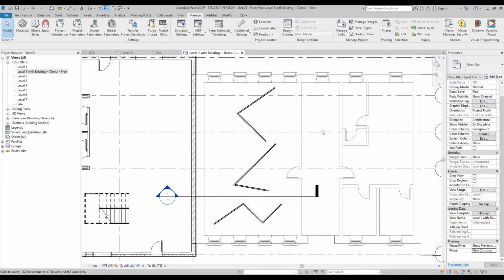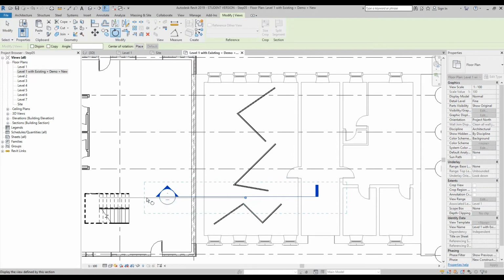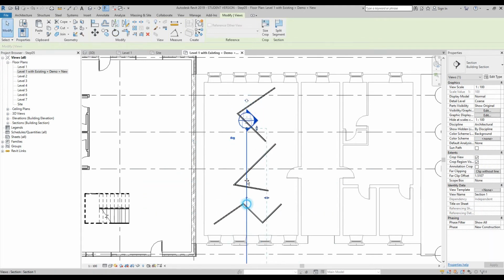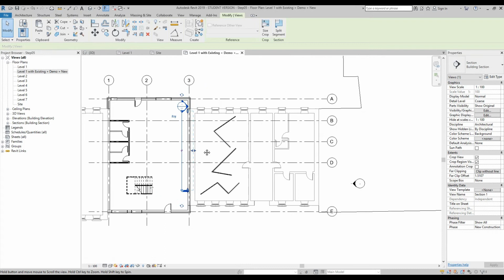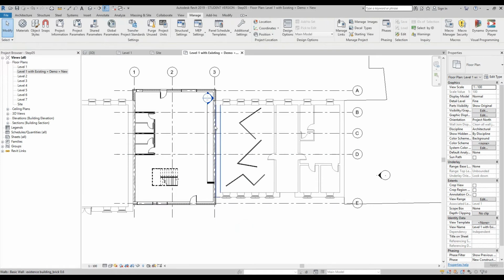So the next thing I want you to do is draw a new section, but as we've already got a section that's currently within our model, we can actually rotate this. So if you select it, the user interface will go green, and if we go to the rotate tool, it will automatically go to the center, which is absolutely fine. And if we click on the left and then go 90 degrees up and then click again, and then if we drag it to the other side and then we get the pull handles and pull it down and then pull it up, and if we pull this slightly out so we isolate that wall, and then if we click in negative space and then double click on the section head,